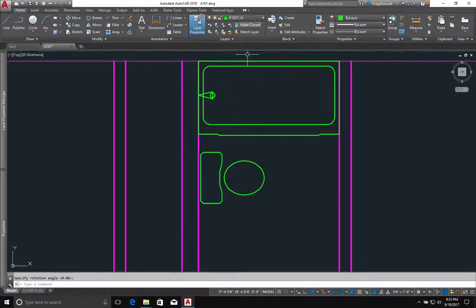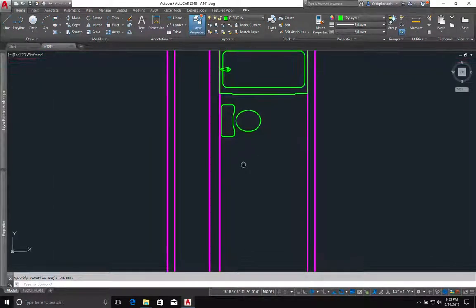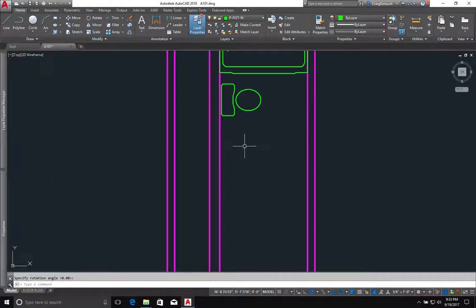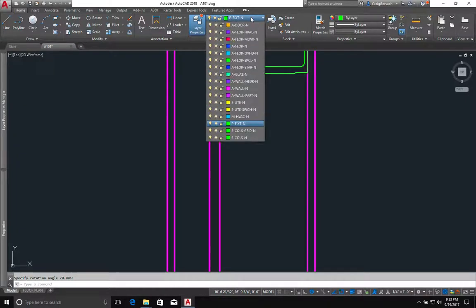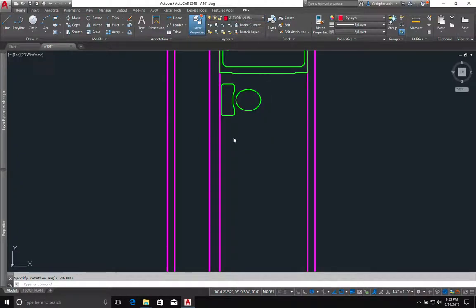And now what I want to do is draw in the cabinet for my lavatory in the bathroom. So I want to change layers, A floor millwork, MLWK. That's all the cabinetry. Whether it's an upper cabinet or a lower cabinet doesn't really matter. And I'm going to start by drawing a line. I'm going to hover over this point to get my object tracking, and I'm going to type 36 inches, come down, I'll go across 24, and then down 36. And it just so happens that this point right here is going to be where the wall takes off and begins going horizontal.